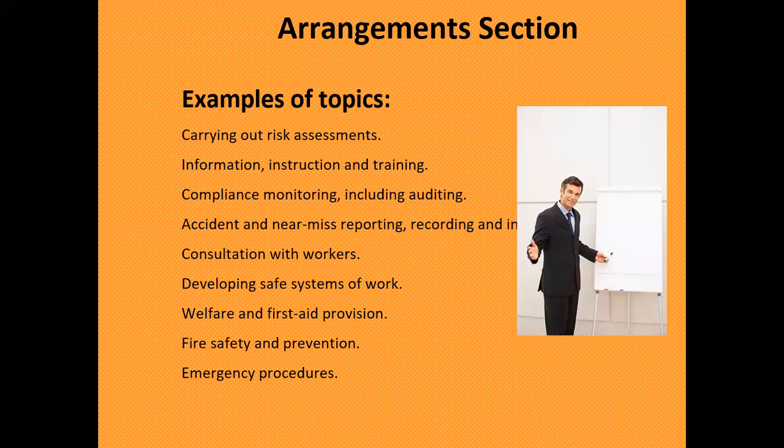Developing a safe system of work, how to perform a job step by step. Suppose in a steel fabrication yard, there are many steps included, like steel coming from the outside, unloading from the trailer, stacking properly, having safe and adequate logistic arrangements, signages, safe stacking, demarcation, and then taking bar by bar and then cutting of the steel and binding of the steel and then again storing or distributing to the different sections. So this is a safe system procedure.